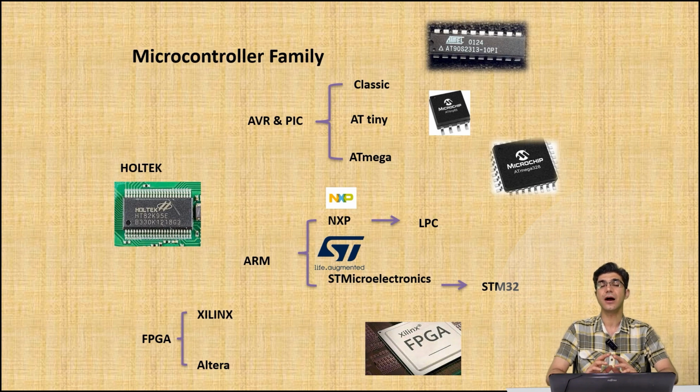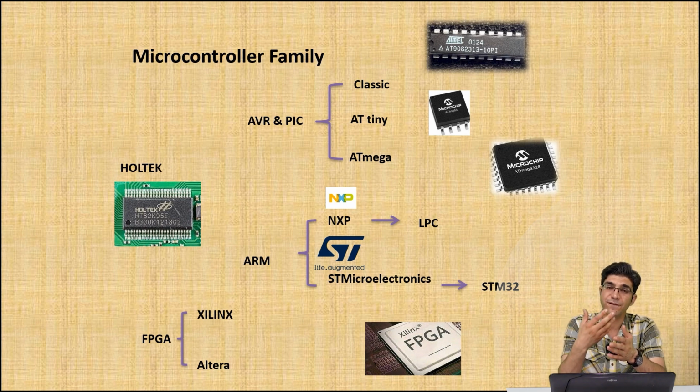Consider any communication systems based on how many, for example, I2C you want, and what kind of USB you want. So based on this you can choose the ICs or microcontrollers you want for your project. It means they have the processors, they have many pins, they have many options for communications, RAM and flash memory and things like this, of course with different prices.